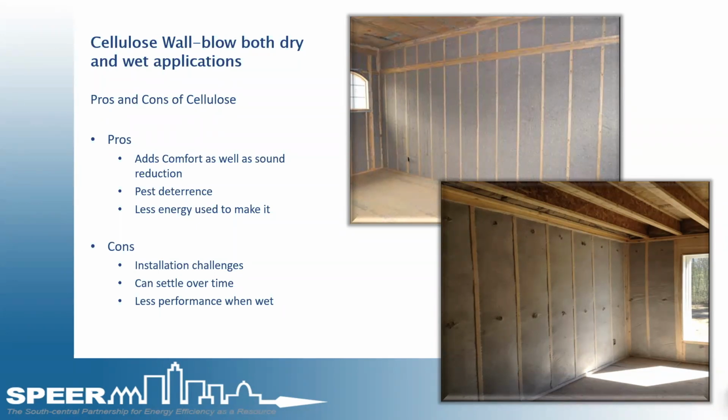The cons are basically that there are some installation challenges. So someone's really got to kind of know what they're doing, and it can settle over time. And it gets less performance if it gets wet. So if it's a high moisture area, you may not want to use that, because once it gets wet, it kind of loses its overall R value. But if you see on the top left, this is sprayed wet and then shaved off at the stud edge. And on the right-hand side, lower right, they actually have netted and blown that in as well. So getting full coverage with that.